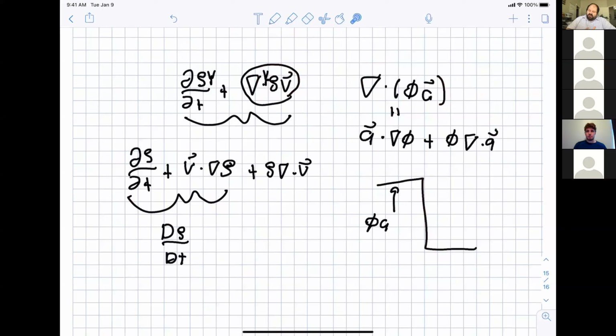Like mass fraction will be smooth across a shock wave. It depends. Like I said, for those of you who've had gas dynamics, the Riemann shock, yeah, for the terms that we have here, all variables except for mass fractions will be changed by the shock. Mass fractions, for those of you who've had gas dynamics, are called Riemann invariants, and that type of Riemann invariant is not changed by the shock.